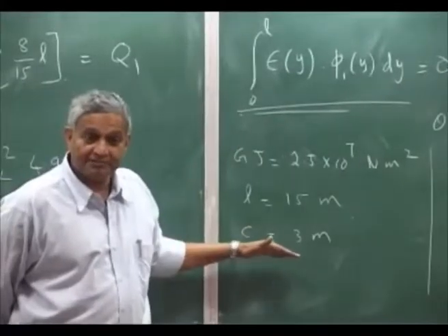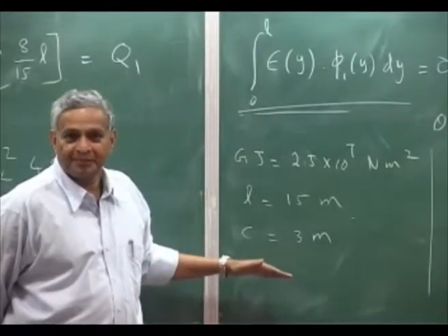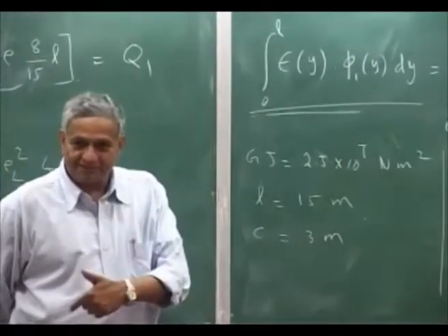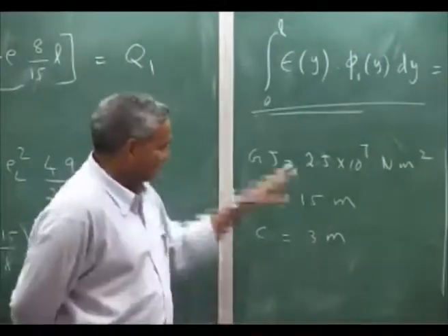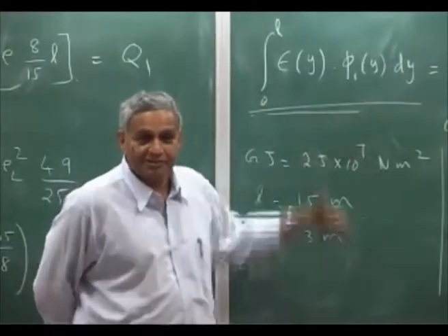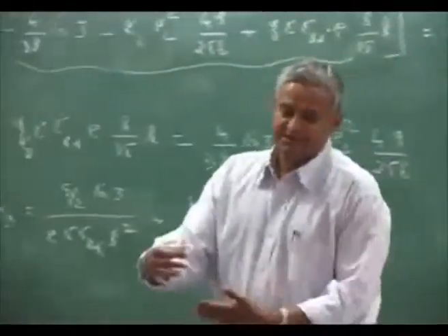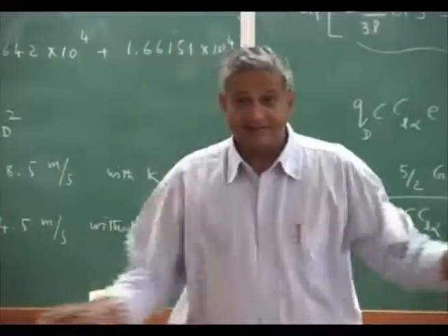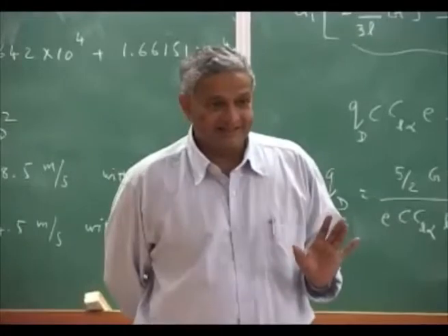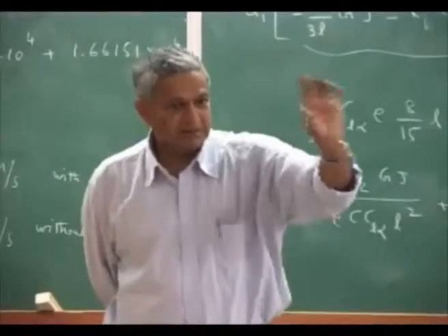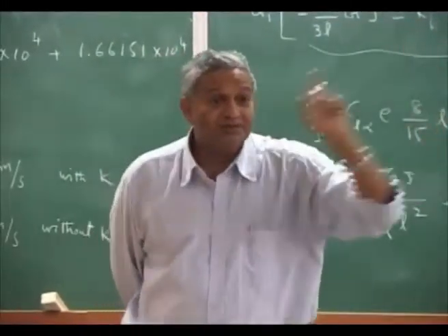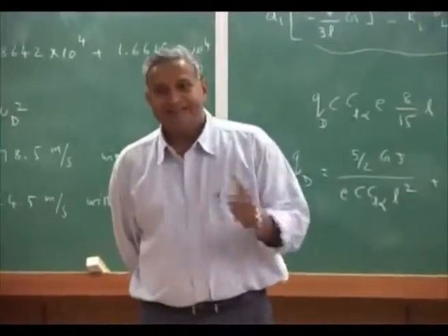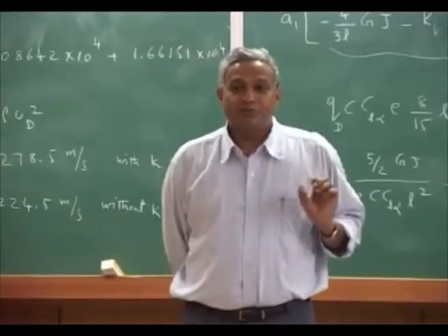The torsion equation will have its own error; you multiply by the assumed function for the torsion and write that. Finally, you will have two sets of algebraic equations, which you solve. That is why you don't try to mix all the errors everywhere. Please understand: bending equation error multiplied by the bending assumed shape function, torsion equation error multiplied by the torsion assumed shape function.